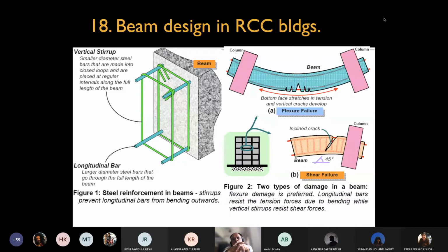Corrosion had set in at the junction where the column meets the slab. And one fine day, there was a sudden failure, because shear failures are sudden; they don't give any warnings. There are no indicators. Shear failures are always sharp, sudden failures.